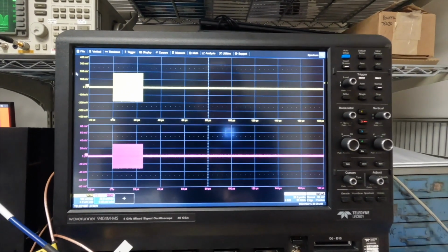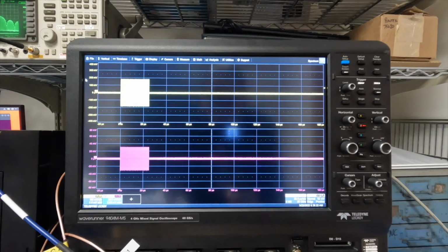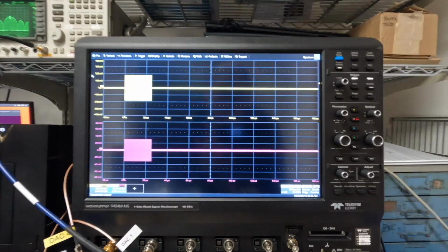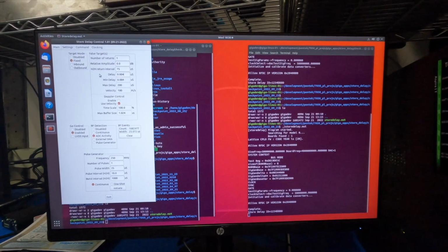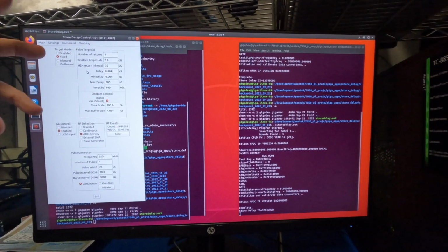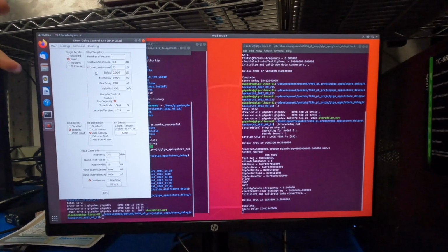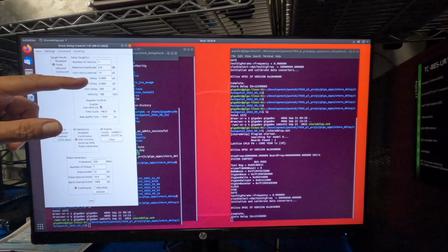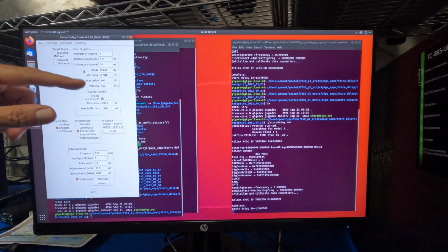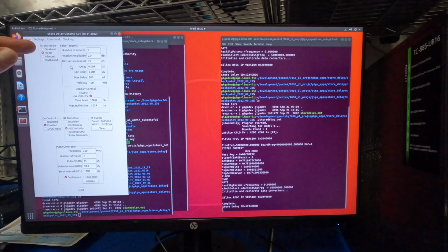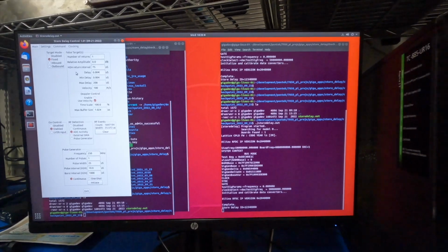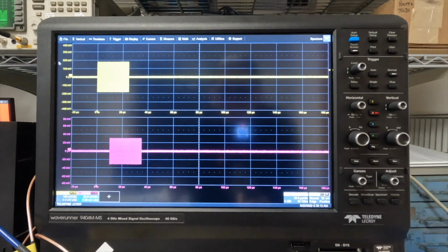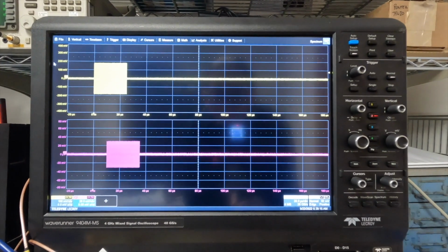if you were doing some kind of range gate pull-off technique where you need a cover pulse close to the actual skin target return before you start walking it away in range. So what we're going to do now is put the first return with a fixed range offset out to 10 microseconds, and then just make multiple returns instead of just the one. So there's your 10 microsecond return.